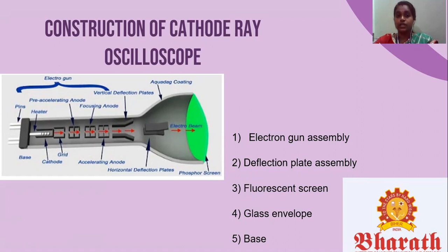The third heading is the fluorescent screen. The front of the CRT is called the face plate. It is flat for screen sizes up to 100 mm by 100 mm and slightly curved for larger displays. The face plate is formed by pressing molten glass in a mold and then annealing it. The inside surface of the face plate is coated with phosphor. Activators in current use are metals such as silver, manganese, copper, and chromium.